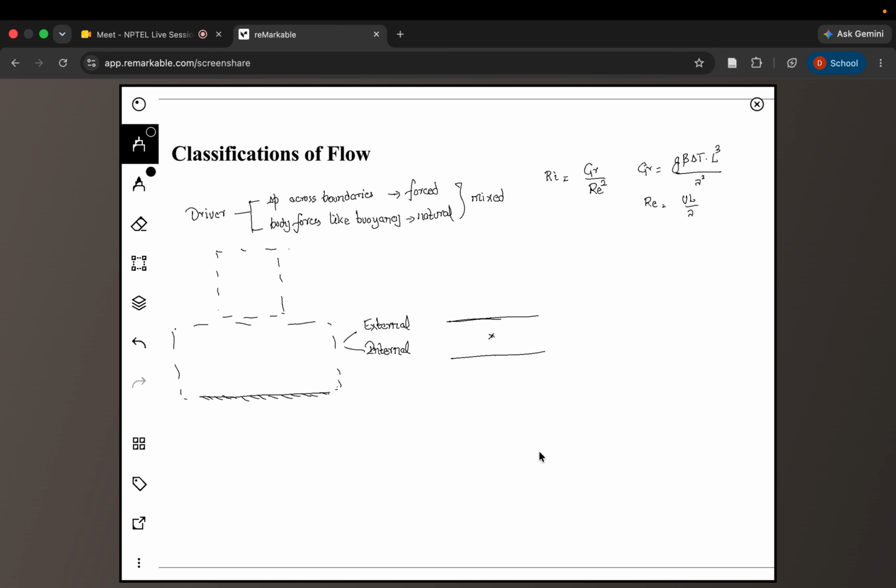What I mean by knowing the presence of both the walls is, if the walls were not there, you would have a certain kind of velocity, and because of the presence of the walls, the velocity would have been affected. How that is affected is something we will discuss once we move on to internal flows. But initially there will be two kinds of regions. There will be a certain region up to which the fluid will not notice the effect of both the walls. So even though it is a flow inside a pipe or a channel, the flow will behave as if it doesn't know the presence of the other plate. It sees only one plate, but beyond a particular point, it sees both the plates.